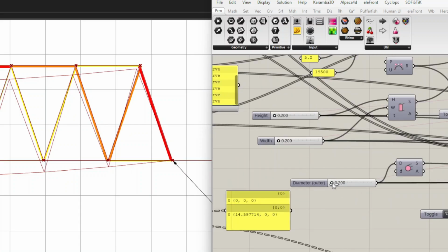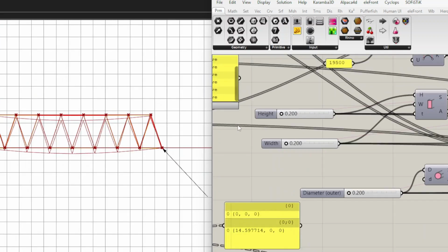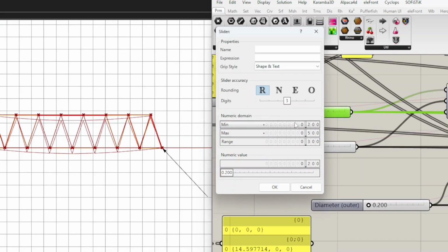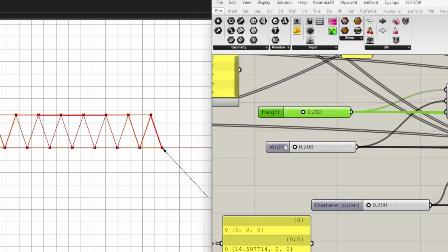Let's review the selected dimensions after optimization. The optimizer reached the smallest dimensions, which prevented it from reaching a utilization factor of 1. Let's reduce the minimum dimension to 0.1 m and run the solver again.